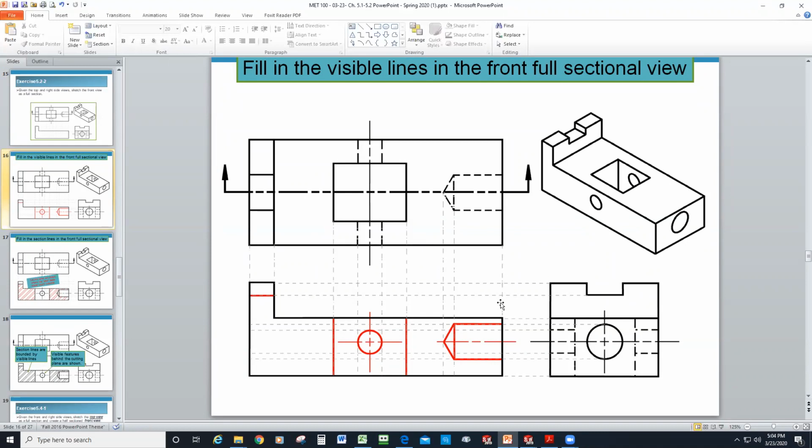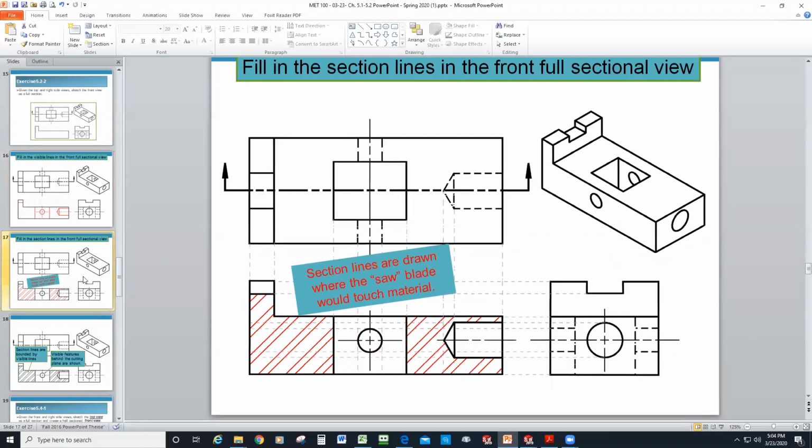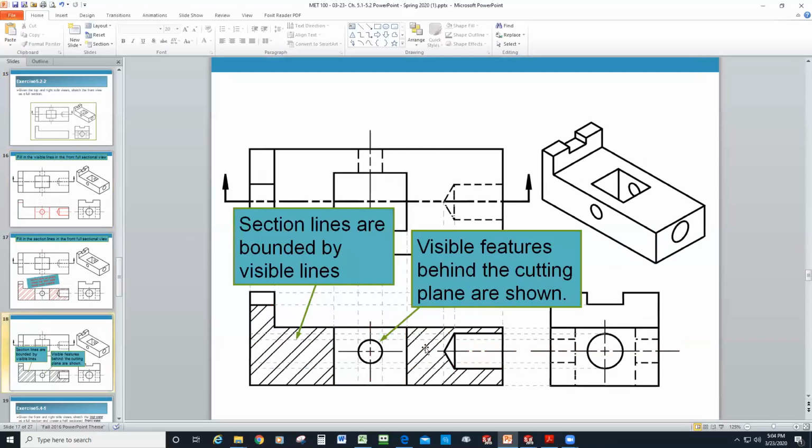And drawing these parts aligned the way they should with the 45 going up this way, so that the spacing from here to here is the same as the spacing from here to here, so that when you transfer over, everything transfers like it's supposed to. We're getting farther and farther away from having to do all this, but it doesn't hurt to reiterate it. And then the last thing you would do would be to add the section lines for the type of material that it is. And I don't know if they said it was steel in the beginning, but these look like steel lines to me.